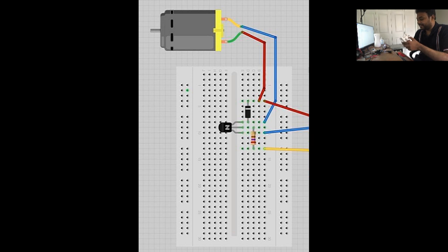Okay. But the problem is, this is not a simple LED. This has moving parts, right? It has some induction behavior, so you cannot simply connect these wires directly to the Arduino. The problem is, with this induction behavior, it tends to draw high current when it just starts, right? Lenz's law, all this comes into play. So when it tries to draw more current, it may damage our IoT device.